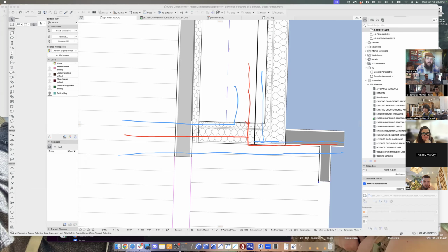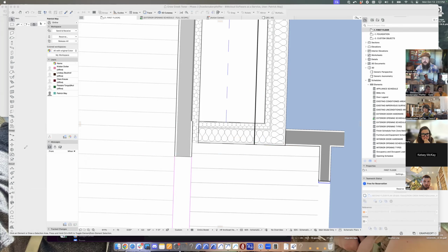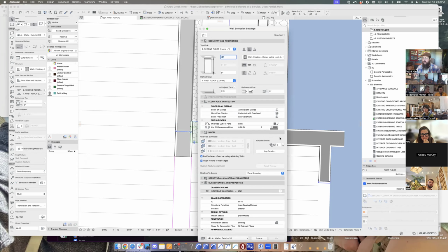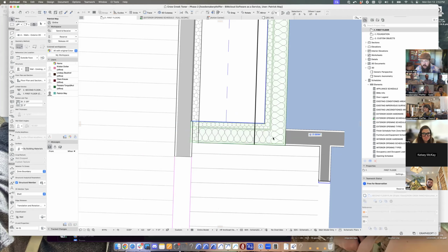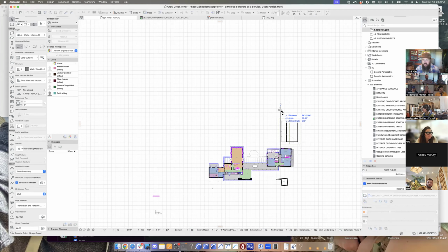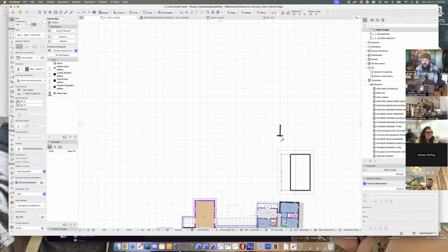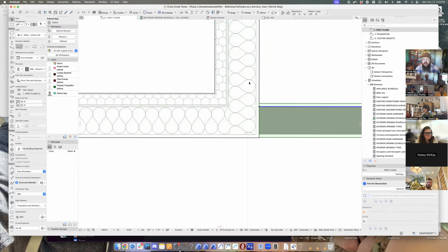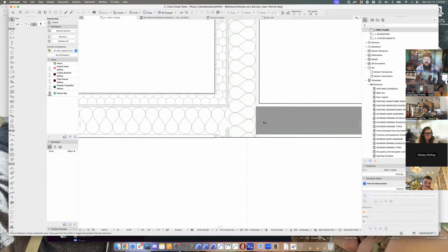Now, what you might need to juggle on top of those reference line interactions is, in the wall settings, this junction order. What order do these three things come together in? I'm just going to grab these three walls as an example because I think these are very unlikely to clean up. In fact, the building's not orthogonal, so I'm going to take that out of the equation right here. Okay, so if these two walls are intersecting with each other, let's go ahead and use that intersect.